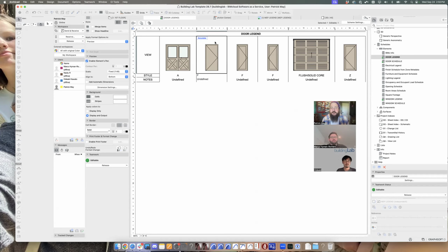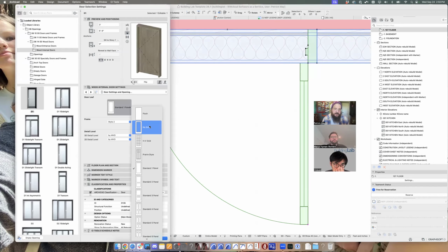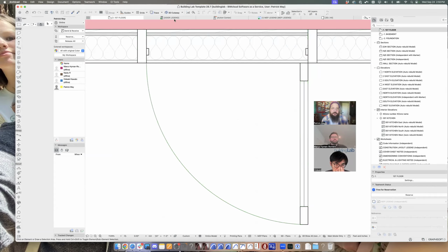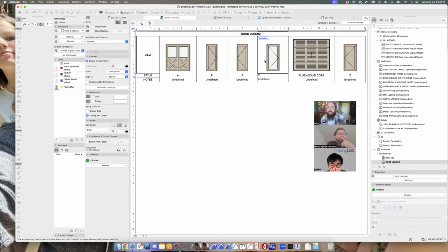So you'd have to select the door here, say show that in floor plan, go to the settings of that door, and change the panel type or whatever the setting was that was supposed to show that. Okay. And you can't change the door from here. You have to go to the floor plan. Unfortunately, no, there's no edit the door settings. You can edit the information that's scheduling to that door, but you can't edit the actual settings of the door.